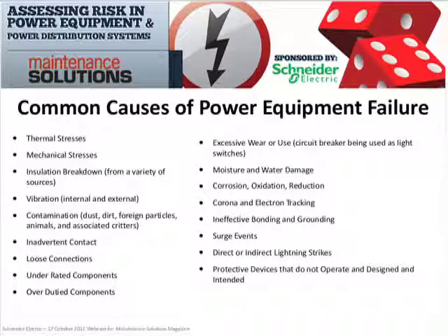Schneider Electric circuit breakers are specifically designed and intended to be self-lubricating. Every time you operate them, the linkages inside self-lubricate themselves as well as blow out the vent ports. If you have a large power switch and you do not operate it, the lubricant in the movable contacts will become an epoxy, and they will not operate after 20 years of not being in use.